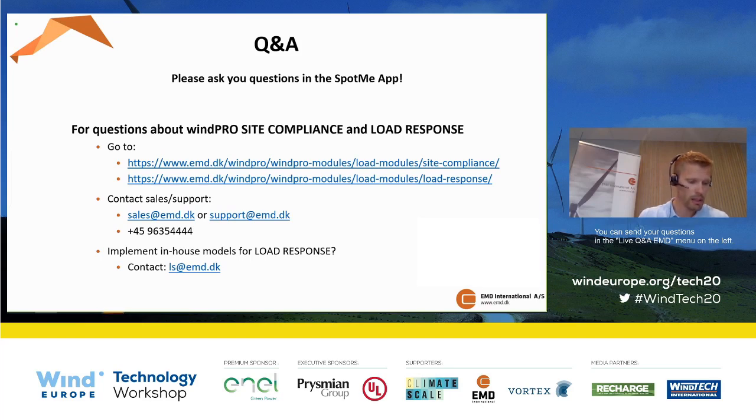And then I think our last question here: how do you see it when the lifetime is offered by OEMs at wind farm level assessment instead of individual turbine positions? Does the curtailment feature support this? Yeah, I'm a little bit in doubt what is meant by the lifetime defined on a wind farm level. I think the lifetime assessment always needs to be conducted on a single turbine and component level.